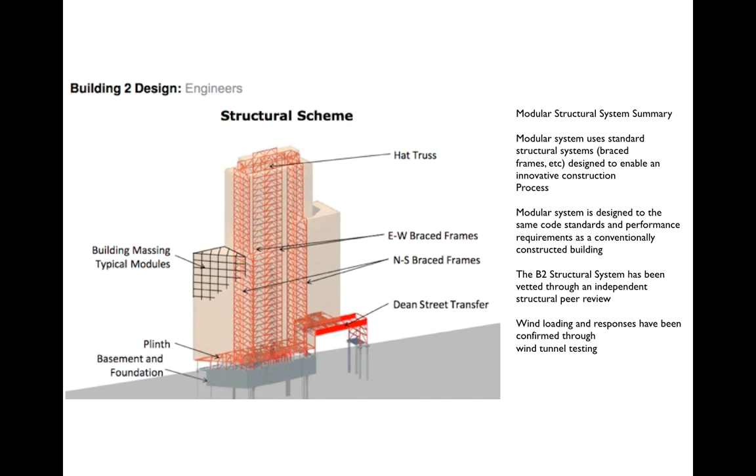Here you see kind of overall. We'll talk a lot about vertical wind trusses. The important thing for the point we're trying to make now is that this takes advantage of steel fabrication, takes advantage of the fact that you can put that steel together using, in some cases, robotic technology, in some cases, manual welding, and that you can create out of lots and lots of little pieces a very, very rigid structure that in this case can support a 35, 40-story building.